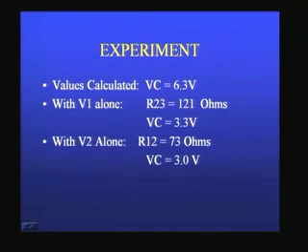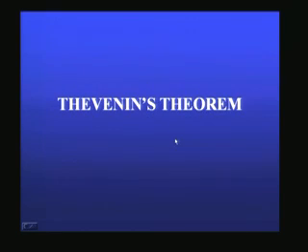Right. So as you can see on the screen, the total voltage was around 6.3 volts calculated. We also measured around 6.2 something, and the 121 ohms, I just now measured 120 ohms, 119 ohms or something for this. We also measured this as 3.2 something and this as 3, and totally that gave 6.2 something. You can see I have not measured this resistance, but in principle we can measure this resistance also in a similar fashion.